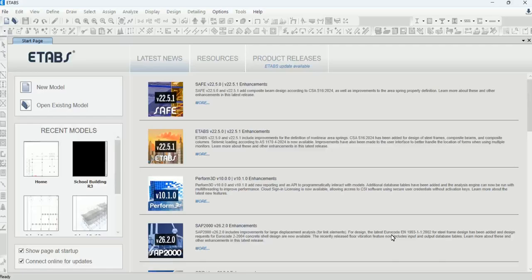structure types and also the locality, because nowadays we are doing the analysis on the basis of earthquake, considering the earthquake factor, and it's a major and significant factor in zone 3, zone 2 and zone 4. Zone 1, normally this factor is not considered. So we are using the building code of Pakistan, UBC 97, which is already incorporated.